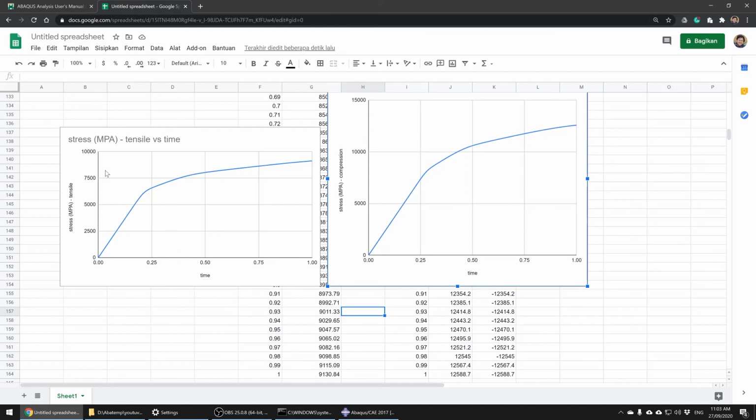So imagine, guys, now you have a question. Imagine I have a tensile test of polymers. I do the tensile test, and I also have a compression test. How do I find the friction angle? Trial and error. You put the tensile test data into your simulation, and you use, for example, a small value of beta, for example 5%, and then you run the compression test. You compare the compression data with your experimental compression data. Does it fit or not? If it's still lower, make the beta higher again. Make it 10 now, and then compare again. It's like an iterative method, right? Until you finally match them.